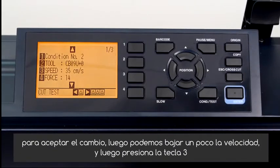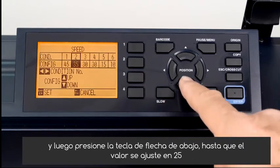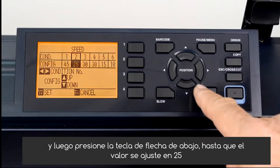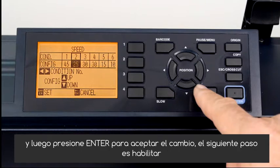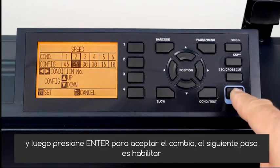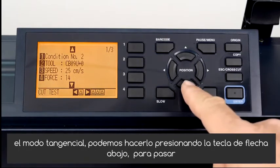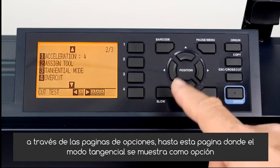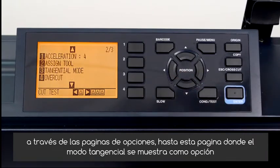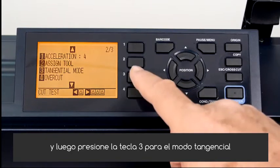Next, we can lower the speed a little, and then press the 3 key, and then press the down arrow key until the value is set to 25. This is a little slower than normal when cutting vinyl, but it helps when handling the corners. And then press Enter to accept the change. The next step is to enable tangential mode. We can do this by pressing the down arrow key to cycle through the pages of options, until this page where the tangential mode is shown as an option, and then press the 3 key for tangential mode.